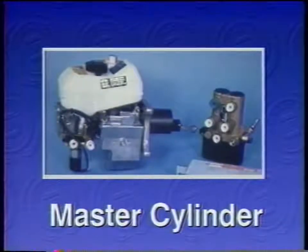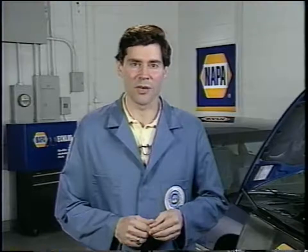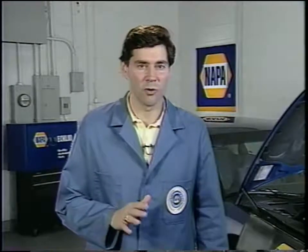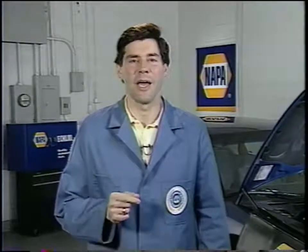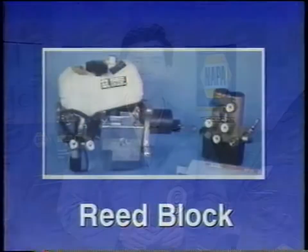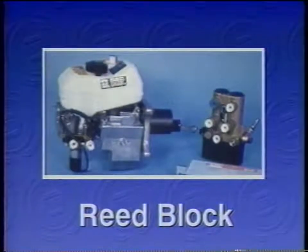of a vacuum booster. The accumulator is mounted upright on the right side of the hydraulic unit and looks like a small cylinder. Be careful when working with this part of the system, as pressure can exceed 2,500 pounds per square inch. The reed block assembly is located in the master cylinder assembly and contains 2 switches for keeping the control module informed about the position of the booster piston.